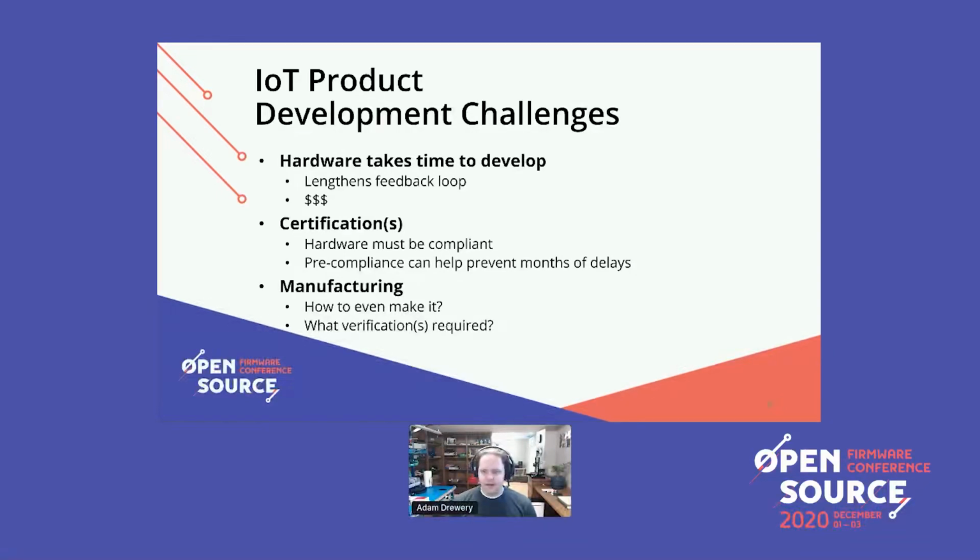The other issue is that hardware costs money. For a round of 10 prototypes with about a week turn time, that's $5,000 or more just in raw materials costs. So if there are any issues, it's really expensive, because it's not just the materials cost, it's also the time spent debugging and waiting for another round of hardware. Also, frankly, statistically speaking, 10 is not very significant. I consider it the bare minimum. But if you can make 10 of something work, you can probably scale up to larger numbers.